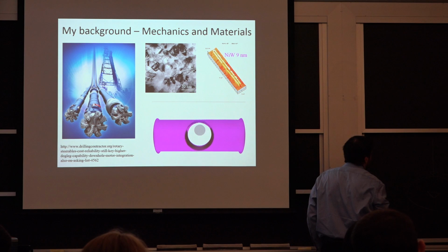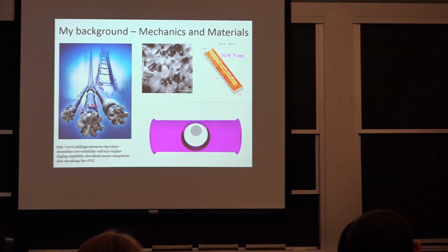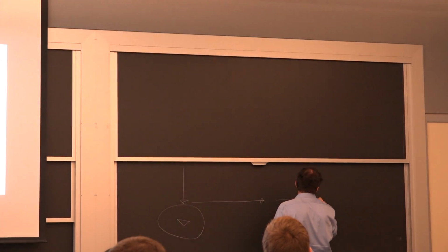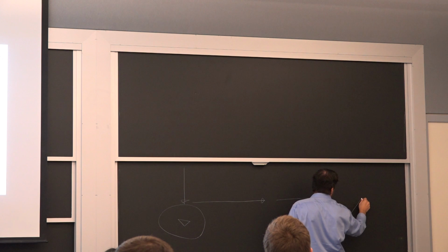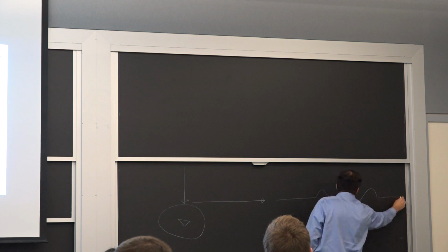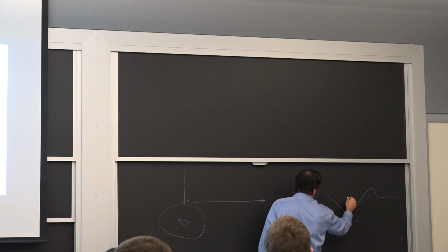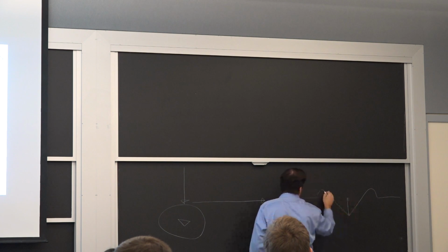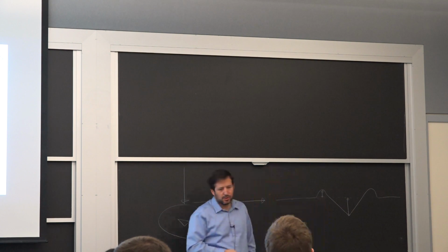What happens during the test is if you have your undeformed surface and a cone tip, you build material on each side. That's what we call pileup, right here. So you have a penetration depth, but you also are lifting up a lot of material here. Now, the amount of material you pile up relates to consolidation.